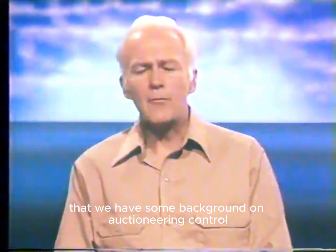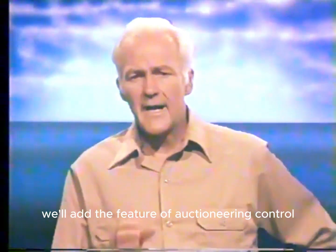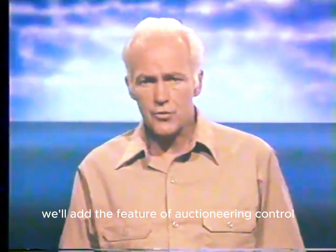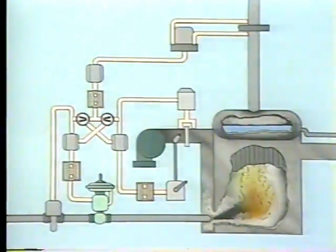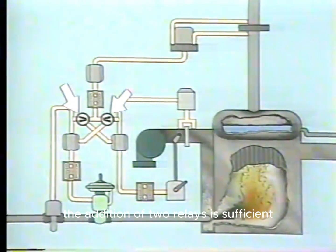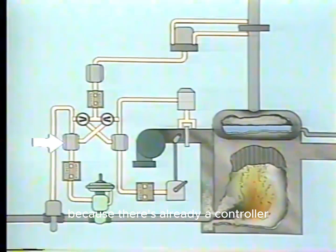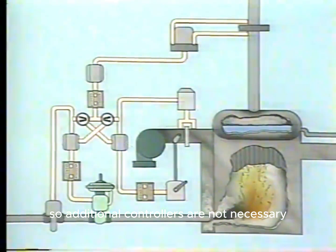Now that we have some background on auctioneering control, let's relate these concepts to the combustion control system. We'll add the feature of auctioneering control to the existing control system and see how it works. For this system, auctioneering control is provided by the addition of these two relays. The addition of two relays is sufficient because there's already a controller for the fuel flow system and one for the airflow system. So additional controllers are not necessary.